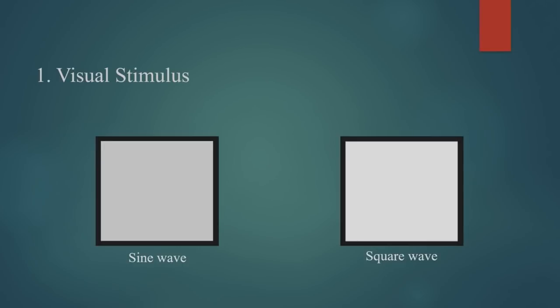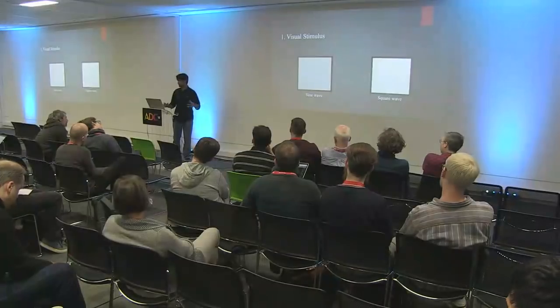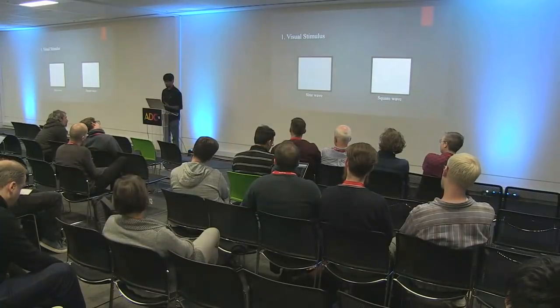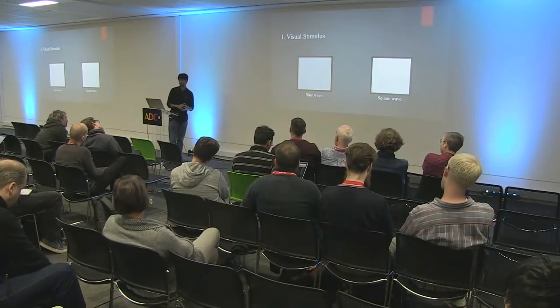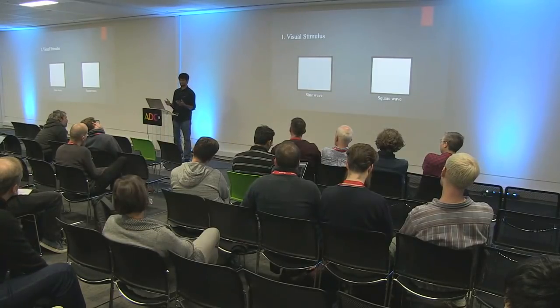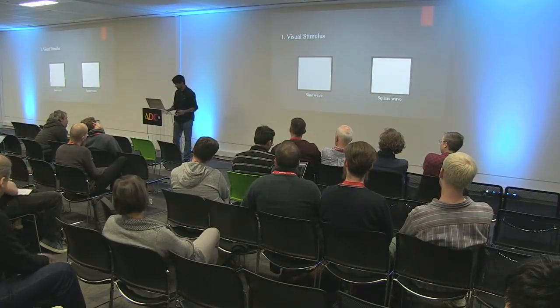Earlier the problem was using square wave stimulation on a monitor of 60 hertz. You could only present frequencies like 15, 12 and 10. The monitor refresh rate needs to be divisible by the stimulation frequency, but after sinusoidal stimulation was proposed, the number of flashing regions on the screen could be increased. And so to realize SSVEP on a commercial platform, we will require hardware accelerated rendering and vertical synchronization, which is achieved through OpenGL in JUCE.